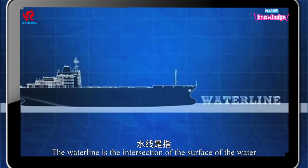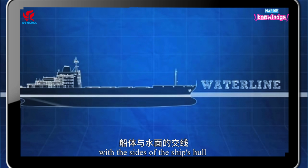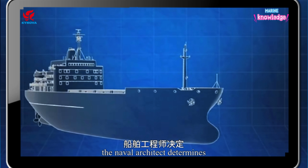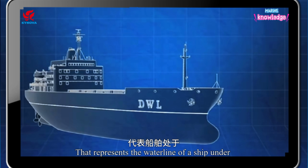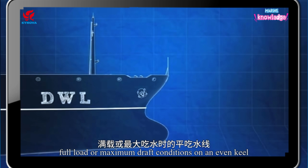The water line is the intersection of the surface of the water a ship is floating in with the sides of the ship's hull. When a ship is designed, the naval architect determines the design waterline, or DWL. It represents the waterline of a ship under full load or maximum draft conditions on an even keel.